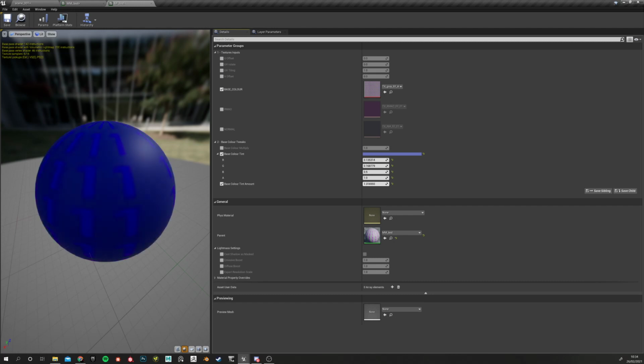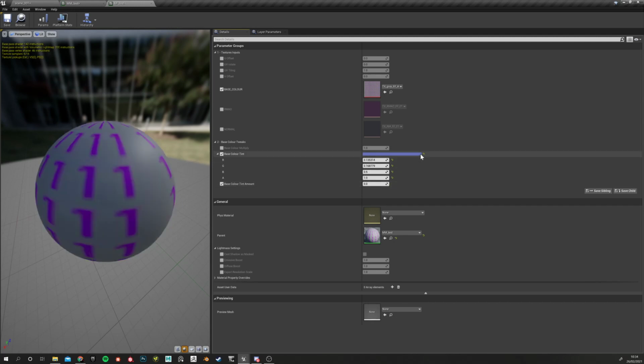Look, and I can even go further. I think it doesn't make sense because it only works from 0 to 1. So if you know that this lerp only goes from 0 to 1, we can cap this number as well to make the UI a bit more robust. So at the moment, when it goes beyond 1, it doesn't do anything. Okay, so we do this. We can tweak this back to 0.5, because that's the default we put inside the master.